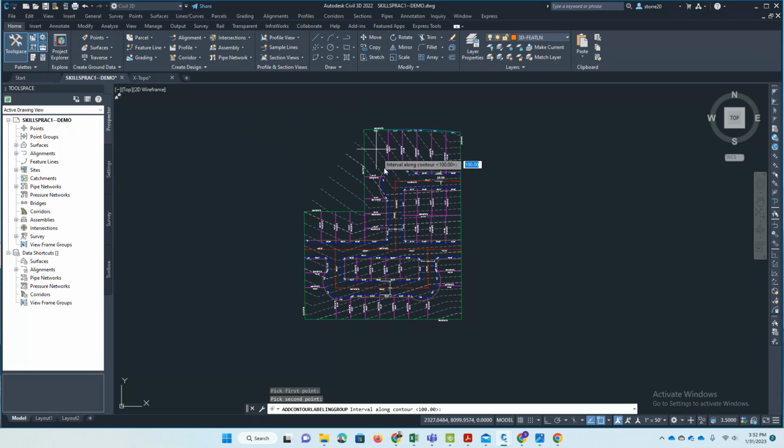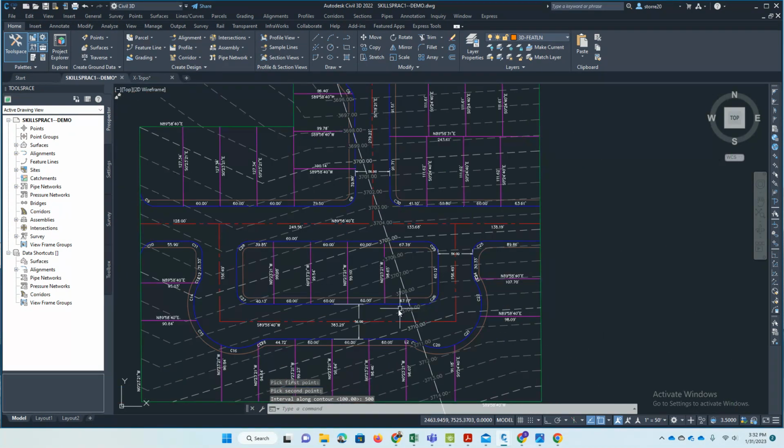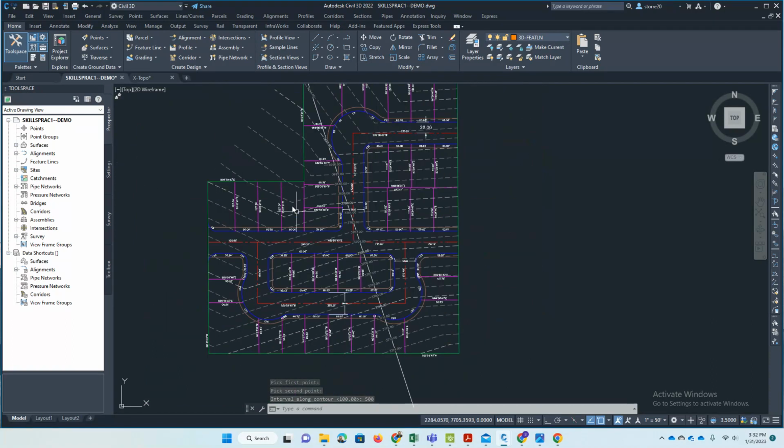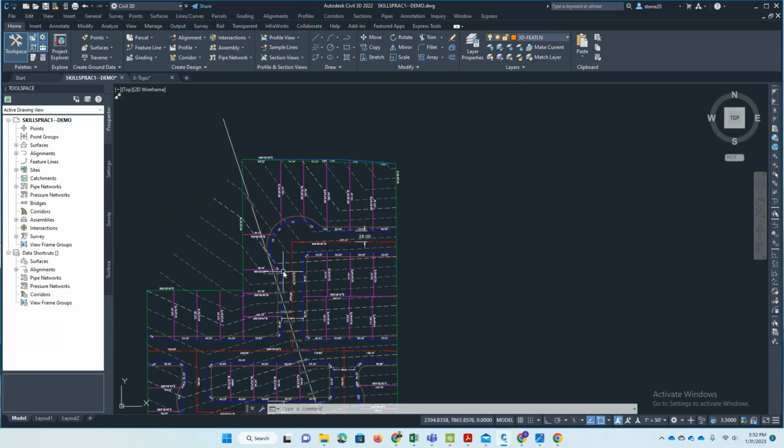Right now, it's going to be from that line, and then along interval, from that line it would label it every 100 feet. 100 feet would be too many. I'm going to probably guess maybe every 500 feet from that point. So label this one, and then 500 feet away would label another one. It's a pretty small plat, so it didn't get to label any more, but that might work.